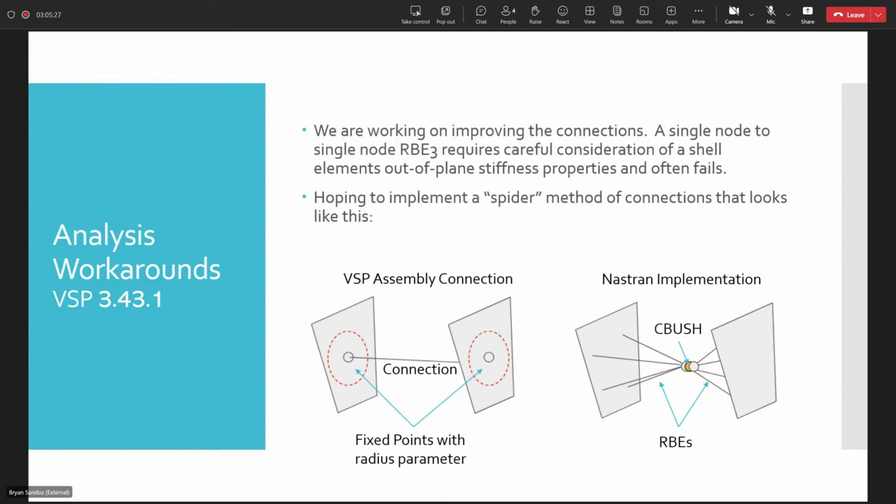With the simple wing that I'm going to work on, it takes about 3 to 6 minutes, but I've intentionally made the mesh low fidelity, and I've intentionally made the VSP aero mesh low fidelity. With some of the more complex cases, like a whole aircraft structure and what I would say is a more common VSP aero mesh density, I've had it run for an hour or more, just mapping the pressures onto the surface.